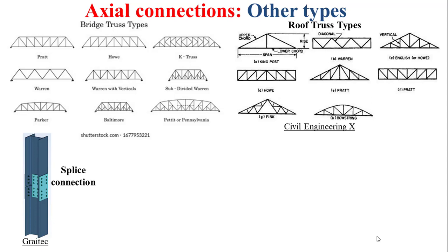There is also the splice connection as it is depicted by the figure at the bottom left of this slide, and in a previous educational video I presented this splice connection as a moment connection since it carries bending moment and shear force, but this splice connection can also be considered as an axial connection since it primarily carries axial forces.